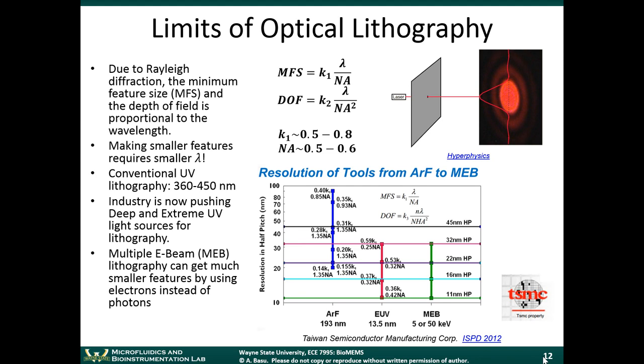With chrome masks, you can get down to sub-micrometer dimensions. But with film masks, you can get maybe 10 to 50 microns. With the cheap laser printer, you're going to get larger than that. But the high DPI laser printers, we get our film masks done at a company out in Colorado. They can get down to 10 micron feature size.